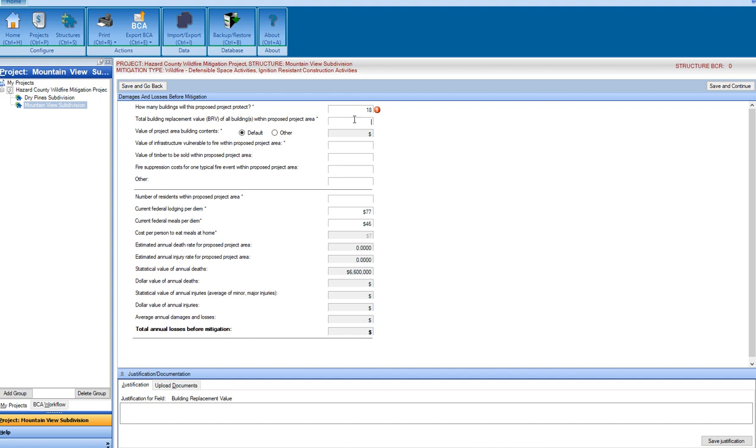If I go into a tax assessor's website at a parcel, the tax assessor's value is divided between the value of the land and the acreage of the land and the improvements on the land, or the buildings and structures. So if you just take that buildings and structures part, that's a totally valid source for arriving at your number here, at your BRV, your building replacement value. But let me show you what I did.